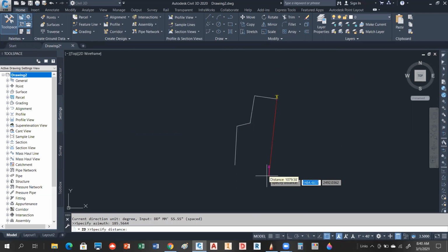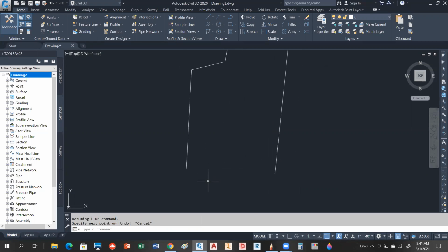And then the distance that's given on this plat is 952.87. Going to go ahead and hit enter. And then you're going to go ahead and hit the escape key. So what I'm going to show you is that if you're coming around a boundary that someone else has created and given all this information, everything isn't going to be a perfect fit because you're dealing with precisions.